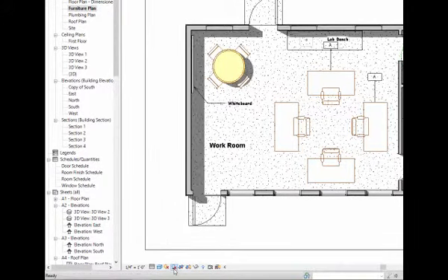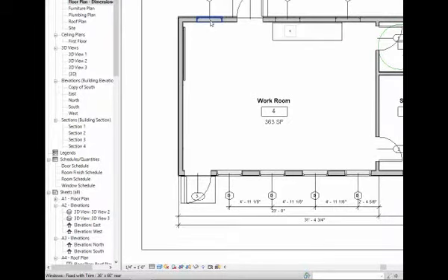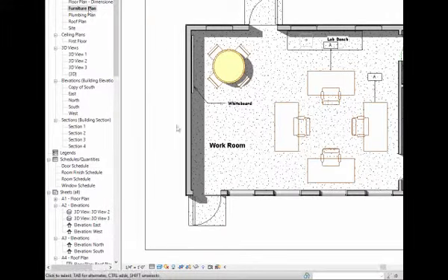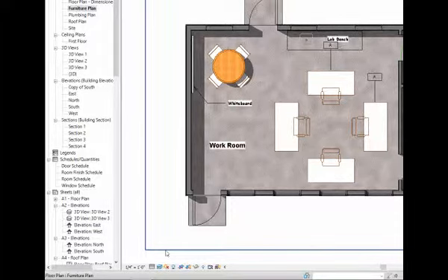You could also, for example, turn on shadows. And that might give you a good sense of depth about the walls. So, those are kind of good. There's a lot of different things you can do. And really, you just have to decide for each of your different views. This might be good from an architectural standpoint. I probably wouldn't do that to my dimension view. My dimension view, I'm going to keep pretty clean and pure so that it really is all about the dimensions, not about the artistic effect. Or maybe my furniture plan, I want it to have a more artistic effect. So, yeah, I'll turn on realistic and give it a color.